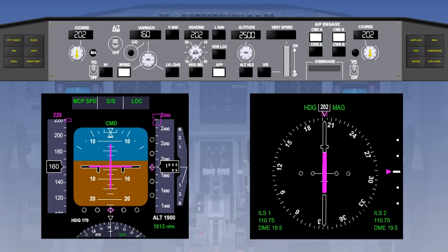It would be normal for the pilot to keep one hand on the control column and follow through with the autopilot, right up to the touchdown. Some aircraft may cause the rudder pedals to be connected in parallel at this time, so that the pilot can also follow through any yaw inputs with feet on the pedals. In this fashion, the pilot knows exactly what inputs the autopilot is making to the flight controls.